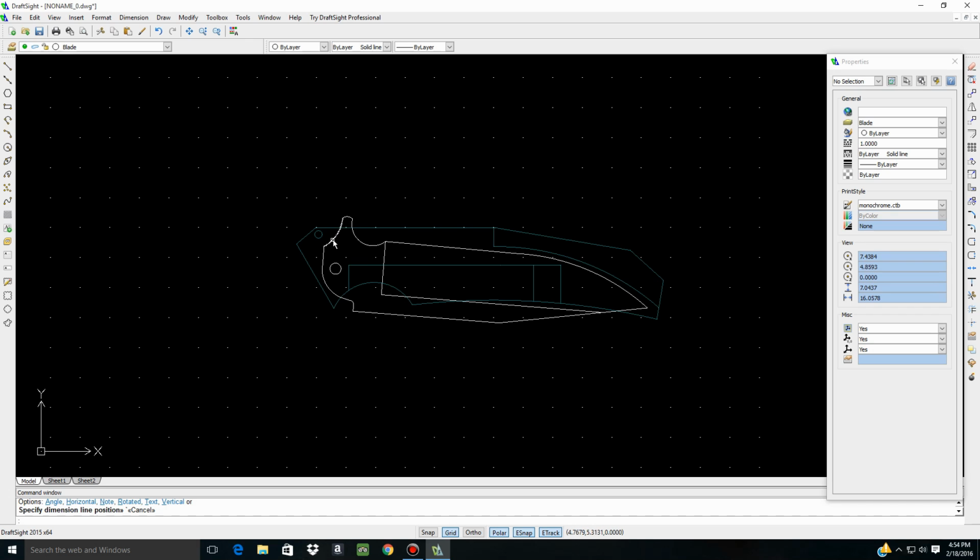Now, ideally you want the flipper as far forward as possible. Some guys even go as far as doing what they call a front flipper, and they put it out here. When it's back here, you don't have a lot of room to kick that blade out. The leverage just isn't there. When it's a little behind the pivot, which is kind of how my design is, you could do a little bit of both. You could push button it, which means push it straight down and load it that way, or pull it straight back. You obviously cannot push button a flipper tab that's out front of the pivot. It's just not going to work. The mechanics aren't there.